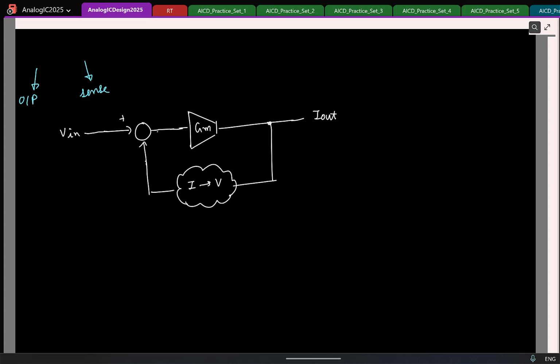So here, what kind of a control source are we trying to make now? Voltage control. Clear? So which means if I were to give a name for this feedback, what will it be? At the output, is it voltage or current? At the input, this is current voltage feedback, you can call it.